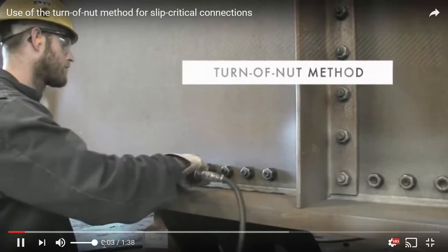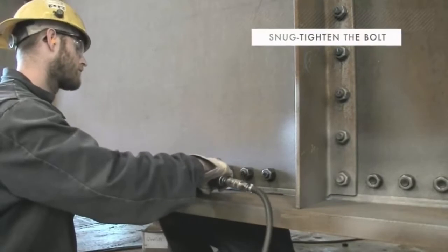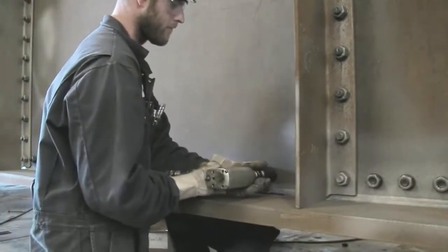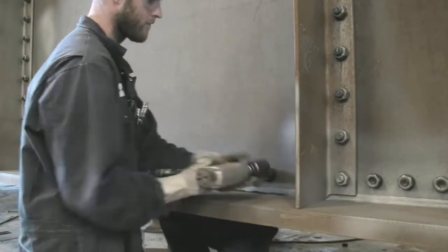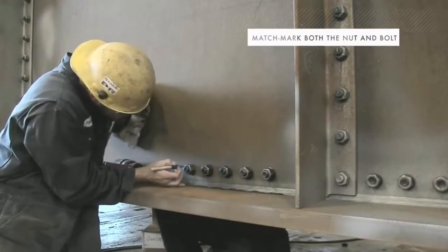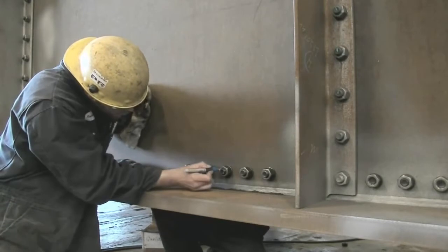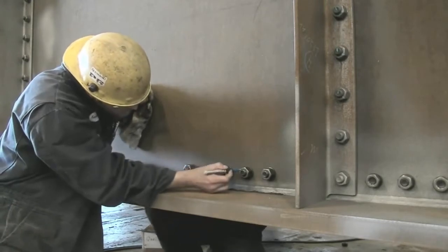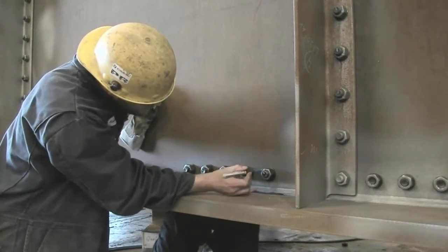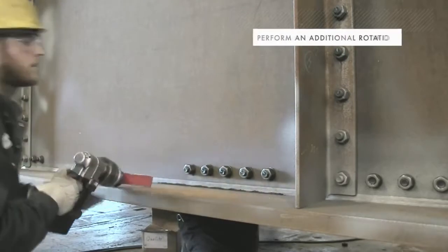So this fabricator is working to install these particular bolts using a slip critical methodology. The first thing that he's doing is getting the bolts snug tight, so it's just a few hits of the impact wrench. Now, if you notice, he's marking the bolt and he's marking the nut. So the idea is once he does that prescribed turn, he'll be able to visually see how much that needs to turn.